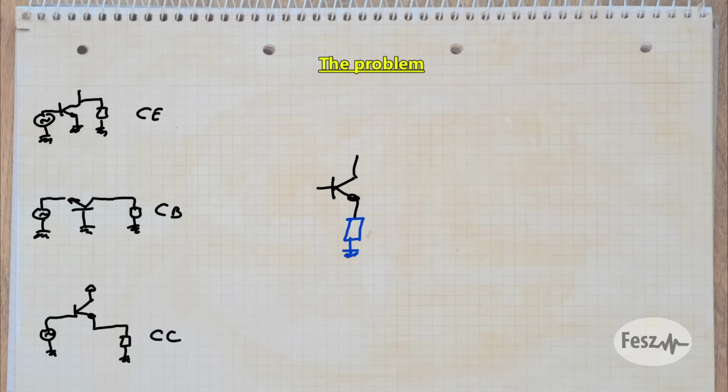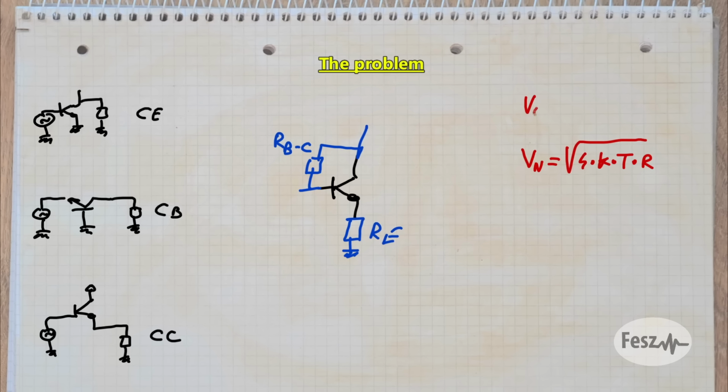While you could use other components, the main advantage of the resistor is the value stability with frequency, so any gain value that is set will be frequency independent. But using resistors for feedback has two major downsides. First, any resistor has an associated thermal noise. Usually, the more resistance, the more voltage noise you get. And second, simply passing the signal through the resistor will create heat, which is another way of saying that you're wasting some of your energy.